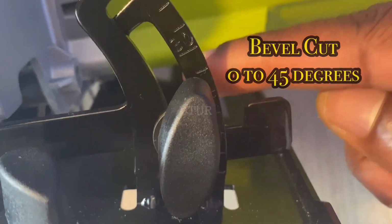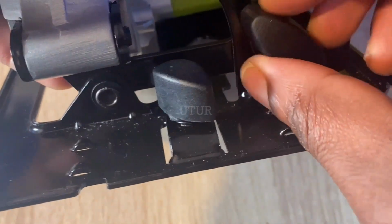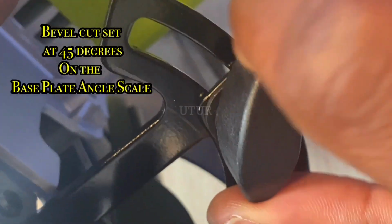The bevel capacity of the circular saw is anywhere between 0 to 45 degrees, and to use this we need to turn the base plate bevel lock in an anti-clockwise direction to loosen the angle scale. The base plate angle scale reads anywhere between 0 to 45 degrees. Tilt the base plate away from the tool until the required cutting angle is adjusted on the angle scale, and then tighten the bevel lock by turning it in a clockwise direction. Do not use the depth of cut scale when making bevel cuts due to the possible inaccuracy.